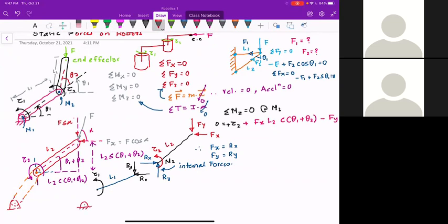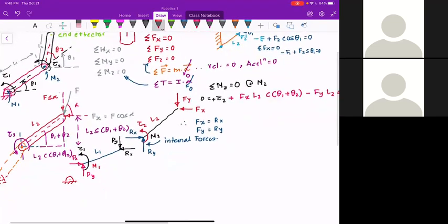As soon as the link is separated from the hinge, you are going to have the hinge reactions. Again, they will come into the picture, and those hinge reactions are going to be something like this. I'm going to call them px and py. Now I need to derive the equation for px, py, and this is my location m1. This is where the moment or the motor is.